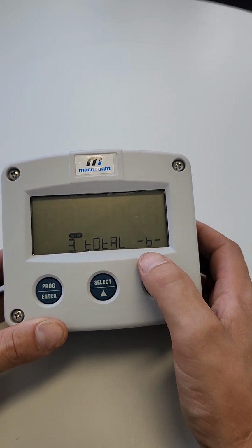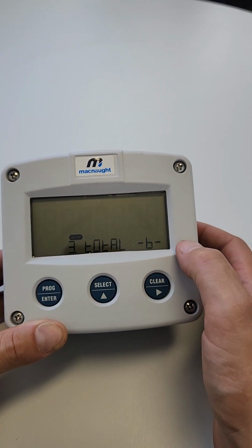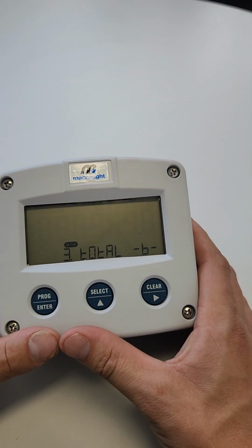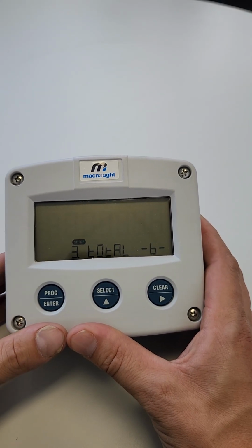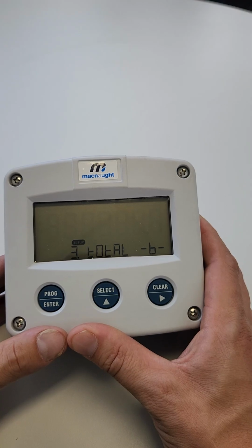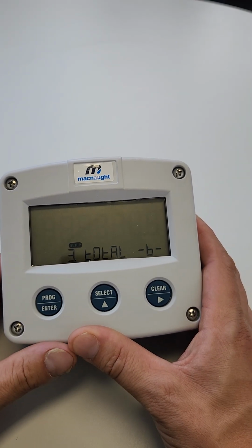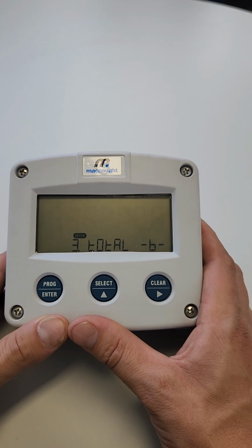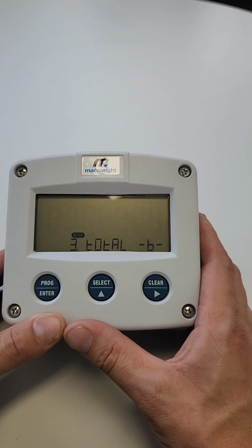It's off to 3, so now I need to do the same, but for the total B. This is for your light vehicle diesel inputs where we're entering our K factor for that. So if you already have the K factor that you've gotten from the pulsar unit itself, a common number used is 52.19. In saying that, all the flow meters can be slightly different.